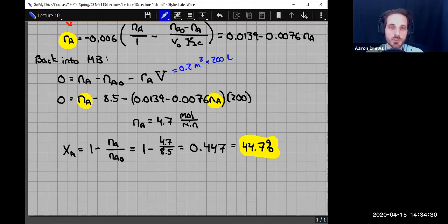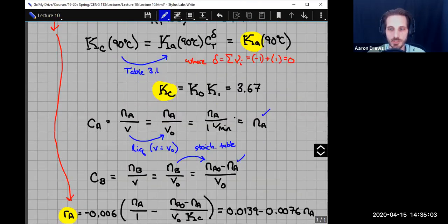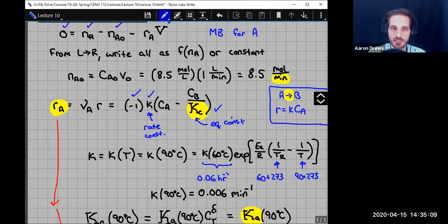So the way that we got that was these three steps, right? We always start here, start with the material balance, then we do some substitutions so that we get to this expression, and then we solve. It's usually those substitutions in going from step 1 to step 2 that take all of the time, and most of that time is dedicated to the rate, right? If I scroll up a little bit, I'll come back down to this in a moment, but look at this chunk of paper starting from about here all the way up to about here is rate law, right? And then the other two terms, the inlet and the outlet, took like one line. And that's not at all unusual.